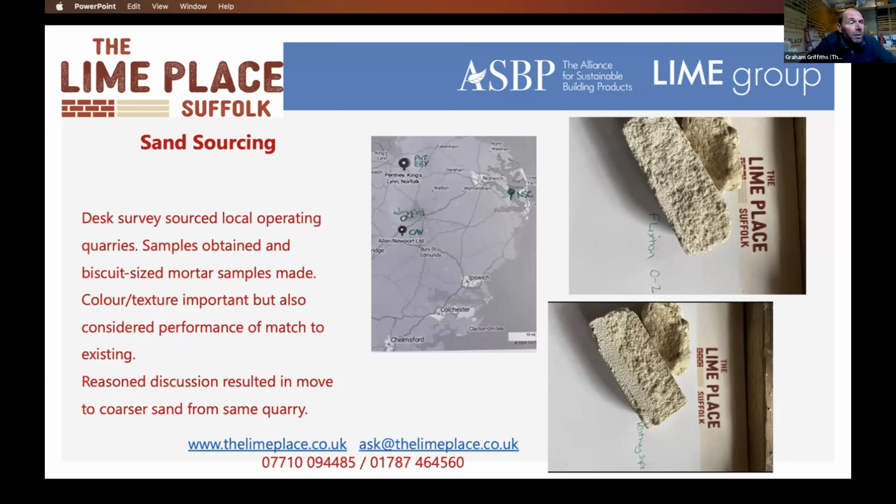The whole interesting thing about lime is its versatility. So we know with a lime building, we can do anything from the floor right up to the chimney pot. We've heard already about floor screeds. Plinth repointing is possible with lime. Dealing with problem salts is possible with lime. Grouts for voids, plaster interiors, rendering exteriors, stone repair mortars, preparation plasters, things like the Eco Mortar R series, right up to above the roof lime mortars designed for that quicker set, so we can set our chimney pot on the top. But the point I'm making is we wouldn't use the same materials in all of those situations, but we can certainly use a lime in all of those situations.